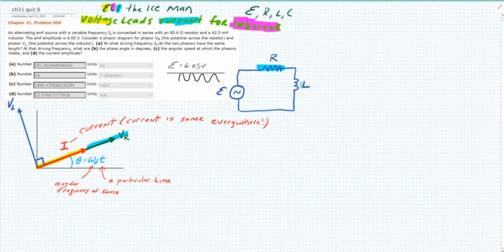Remember what an inductor does. An inductor has some electromagnetic properties. It has some inertia, it chokes the current. In fact, a lot of times inductors are referred to as chokes. And remember, a capacitor has a certain profile too, but a resistor is just sort of a dumb physical device. There's nothing exotic from an electromagnetic point of view about a resistor. The current going through the resistor is just completely synced with the voltage drop across the resistor.